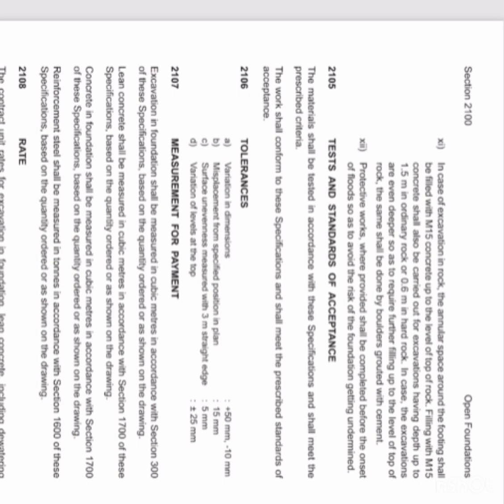In case the excavation is even deeper, further filling up to the level of top of rock shall be done by boulders grouted with cement.